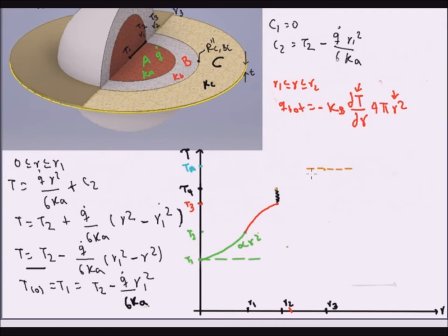Here is where we get to see whether we made a mistake by assuming an adiabatic fin tip, because if the fin is not long enough, then your temperature at the edge might not be quite the same as your surrounding fluid, and you will actually have some heat loss at that point. Please remember that we are just plotting it like this in this case because these are the boundary conditions that we used, but in reality, and in a test, you're expected to have the right boundary conditions, which are that at the fin tip you have some heat loss.